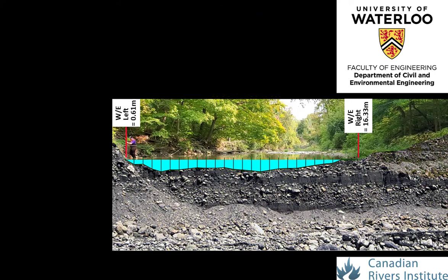Here, by way of example, the technician chose a spacing interval that was convenient to keep track of in the field to reduce application error. Although this resulted in 26 vertical panels along the cross-section, there is nothing wrong with increasing the number of panels measured above 25 to 30 if it improves the accuracy and decreases user error.